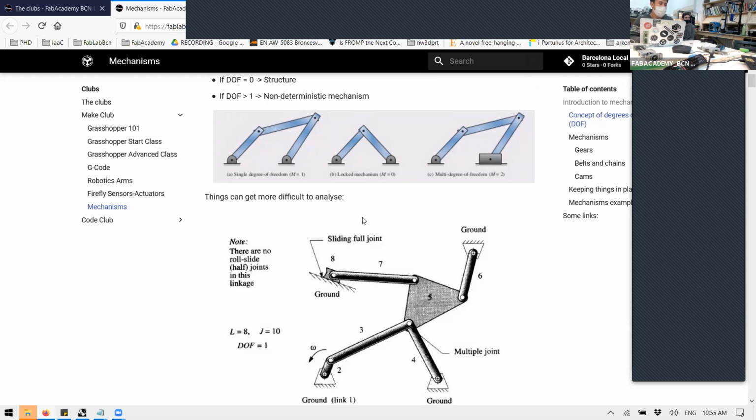For example, this is a dry bearing that doesn't have any mechanical movement, but we use the friction of the material. Plastics in general have a really low friction coefficient, and if you make them thin enough, you can make things slide against each other with a little bit of lubricant. And some plastics are self-lubricating too. That means you don't need to lube it.